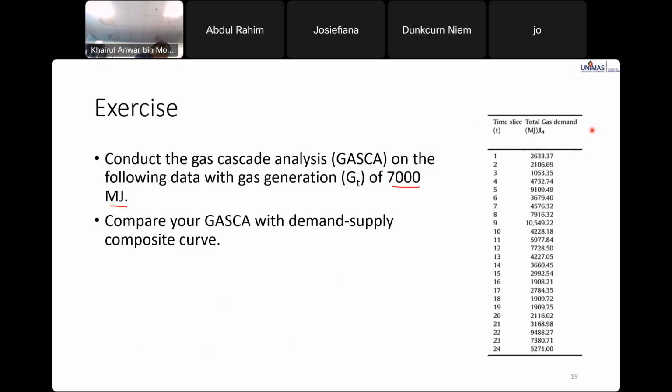From the 24 values of net gas energy, you segregate or categorize it into charging and discharging energy for CT and DT. Then you do cumulative energy QT one by one. After that, you start your iteration using 0 Q initial, so 0 megajoule. You get the Q final.